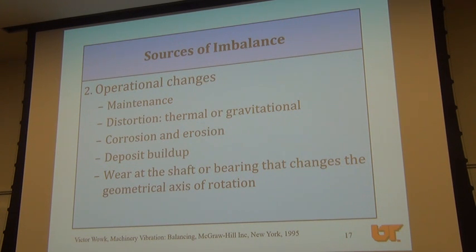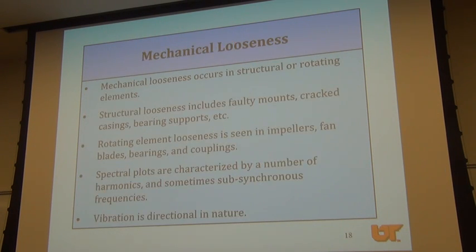They're supposed to be perfectly round, right? So when they go out of round, then you will have more vibration or higher forces acting between the rollers. So those are all operation related, and they could be gradual. You don't have to see these things when you start the machinery. Maybe it takes a while before you see the vibration in these components.